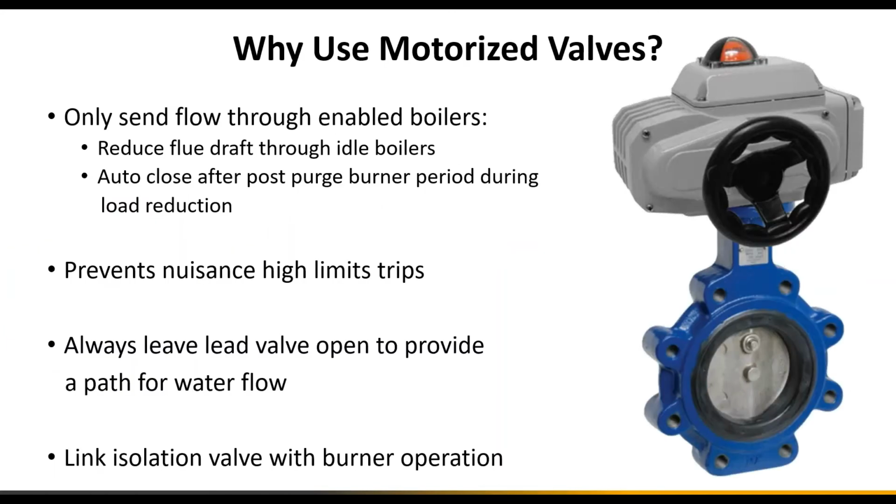Moving on, one key aspect that I briefly mentioned, and I just want to focus on briefly here, is the use of these motorized valves. First of all, these motorized valves ensure that we're only sending water through a boiler that's an active part of the system. So we're not going to have a boiler become a large radiator in a mechanical room, just sitting there giving off heat without being an active part of the system.